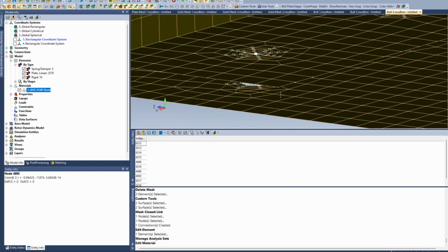But the other issue with doing thermal stress with RBEs is that it may still cause high and fictitious stresses. So one of the techniques I have seen used is to use a large massless beam and apply a thermal expansion coefficient to that, instead of rigid elements. And there's a command in here. I don't think. Let's see.